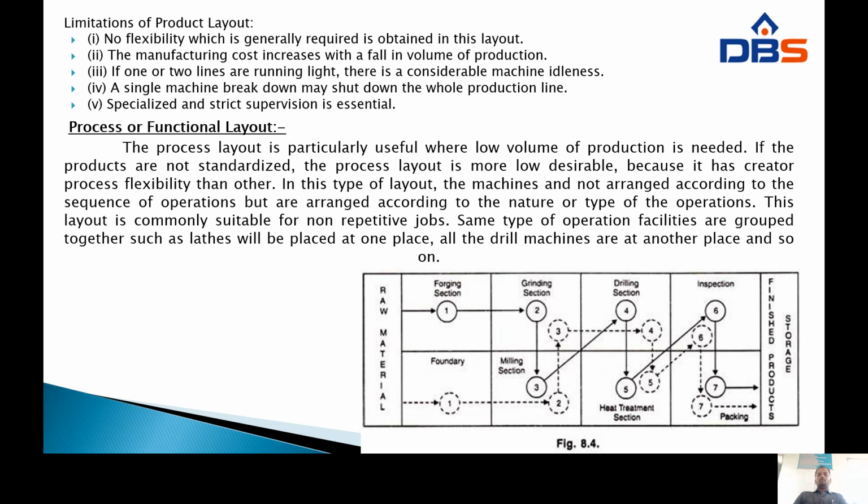Further, the number of processes, the replacement of machinery, or the sequence of operations is not fixed. The production cost of an item is also very high compared with the product layout. The functional layout will develop a component which may be a peculiar one, but the cost is high since it is not following a particular route of production or a standardization.